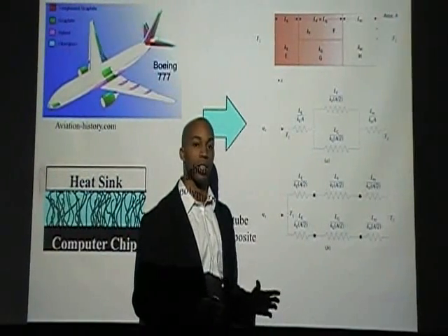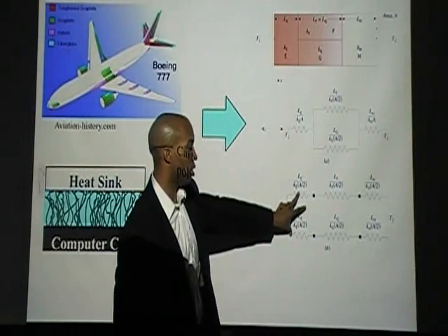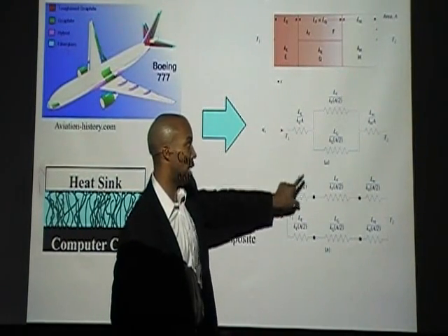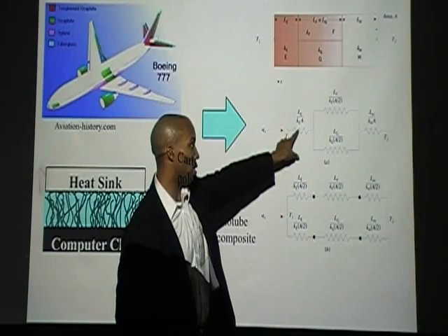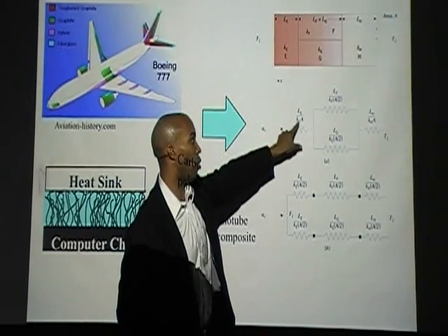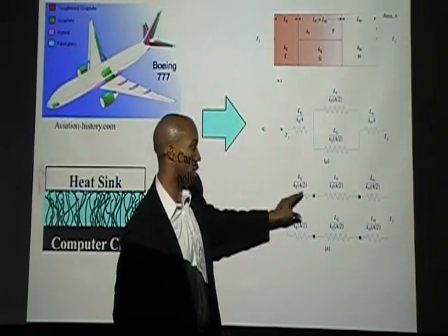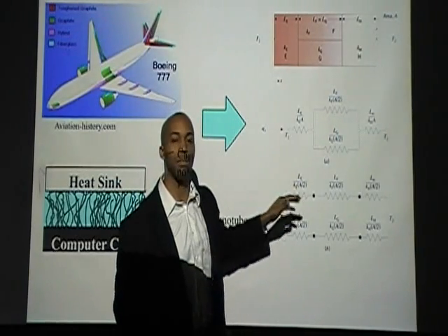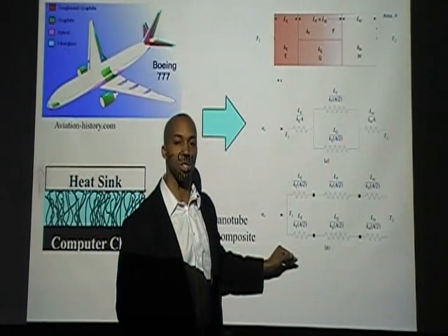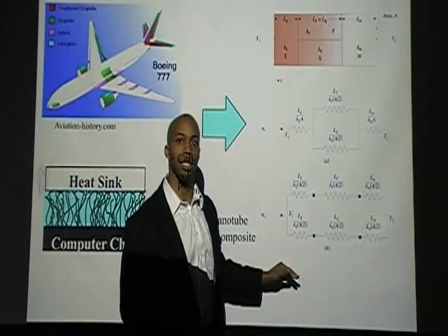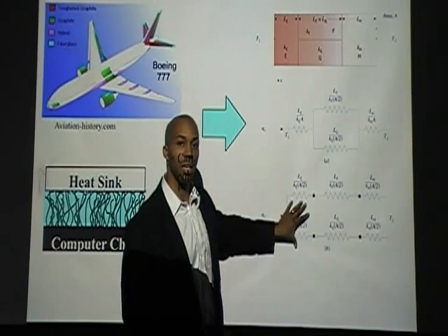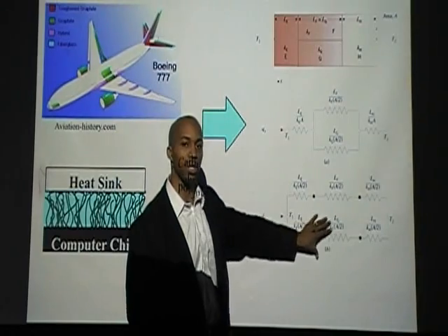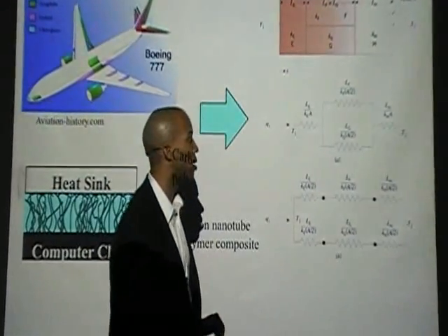We didn't do any magic here, because these 2 circuits are the same as this one circuit. For this one circuit, it's L over kA, and for these 2 circuits, it's L over kA divided by 2. We just divided the area by 2, divided the resistance basically by 2, and broke it up just so we can represent our circuit in a different way.